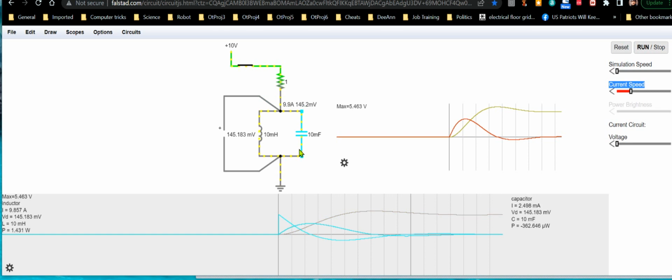There's no dots flowing through the capacitor. It's got 0 voltage across it. All the voltage is actually across the resistor, which down in this little area you can see. It's almost 10 volts, but there's very little voltage, if any, across the inductor at this point. In fact, soon there will be no voltage across it. It's like 140 millivolts and falling.